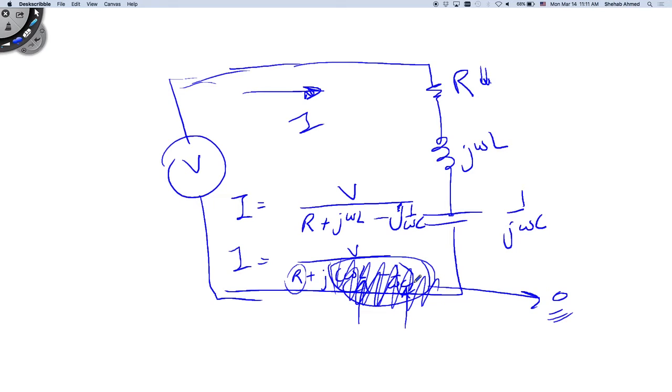That's why when you design a generator or a motor or any rotating piece of equipment, you want to make its running speed far away from the resonant frequency of the system. Otherwise, if you make its resonant frequency the same as its rated running speed, then you put in a small stimulus, supply a small amount of electrical power, and it will spin like crazy, right? Uncontrollably.